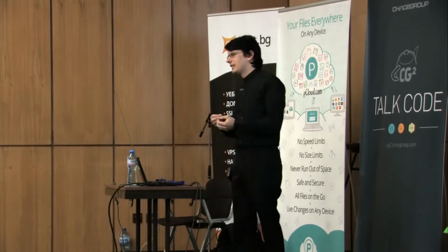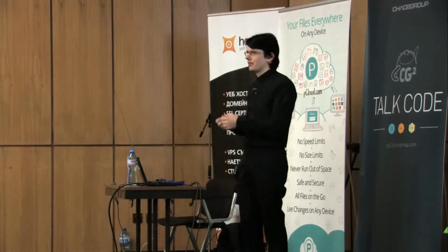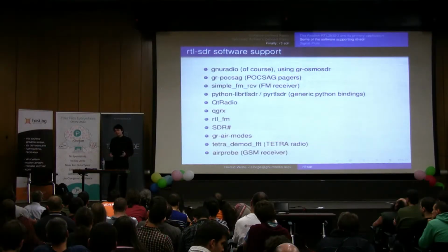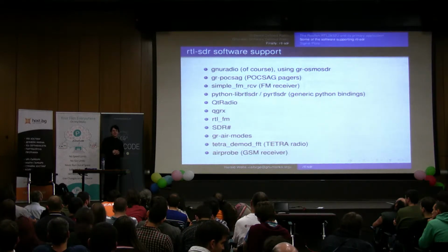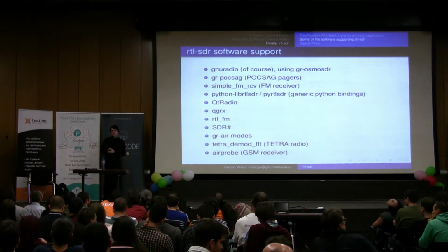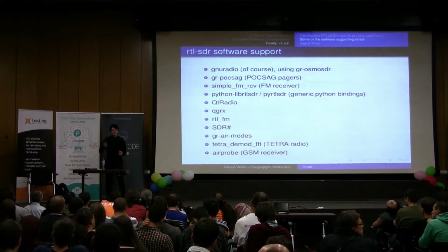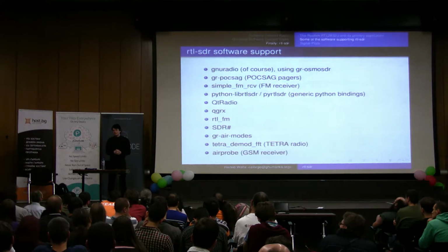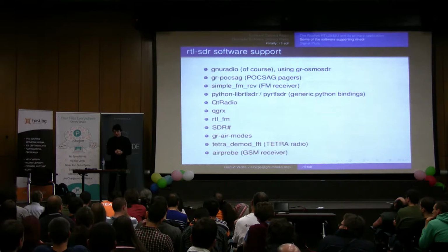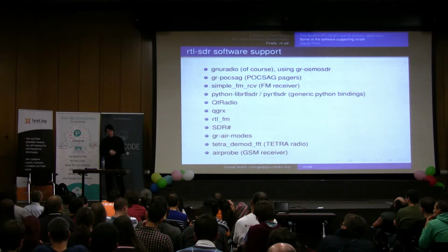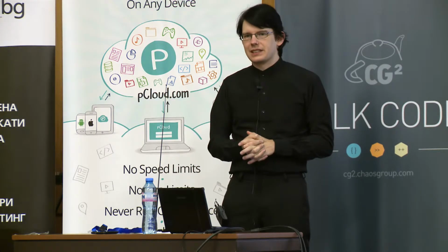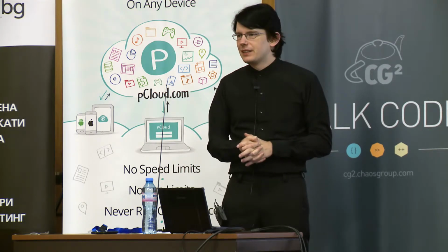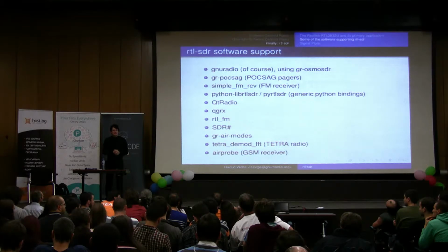Because if you have long coaxial cables, they have lots of losses, or the cables have to be very thick and not very easy to install. But putting the receiver directly at the antenna and then forwarding digital samples over Ethernet is, of course, a very nice solution to this problem of directly capturing at the source and avoiding any antenna cable losses. Questions?